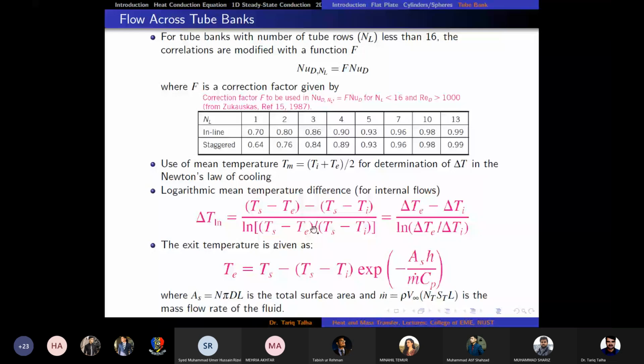Okay, yes, Charis. Sir, if at every step, after every tube, the air pressure changes, we could calculate Q accordingly and add them all up afterwards? Absolutely, you can do that, but if you have got 100 rows, then good luck with that. And why would you need to do that? It is doing your Gauss-Seidel iteration on paper.